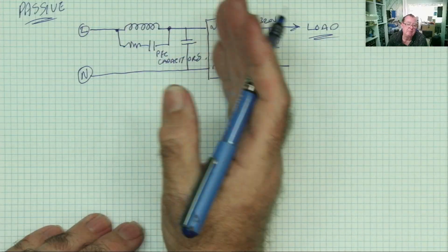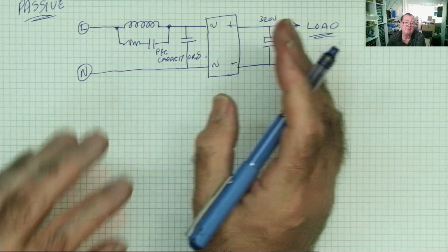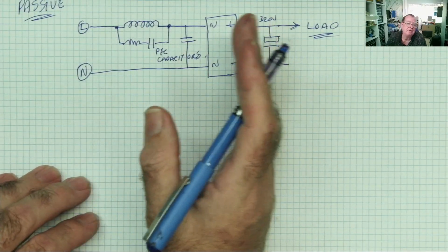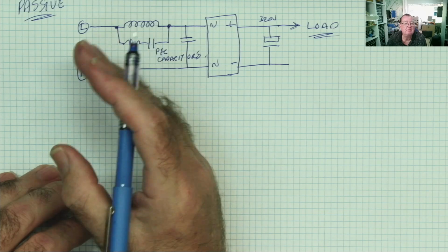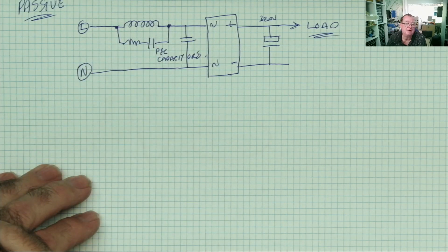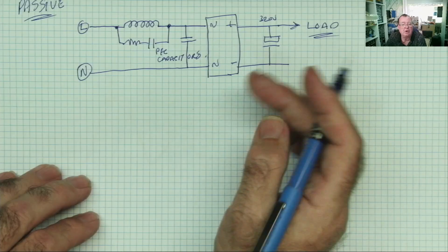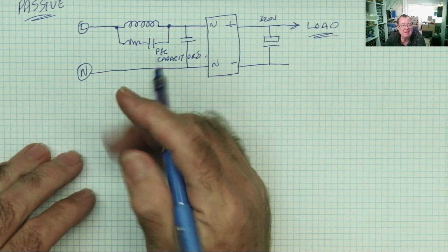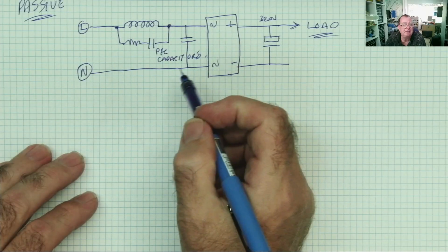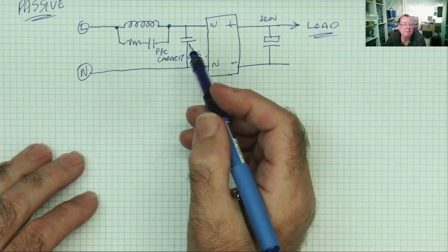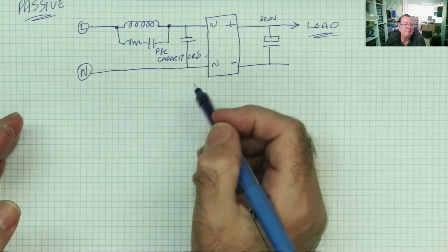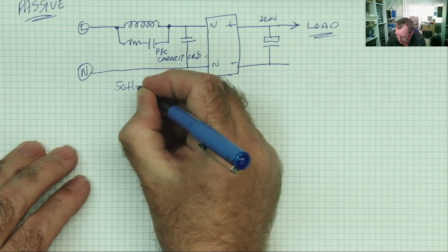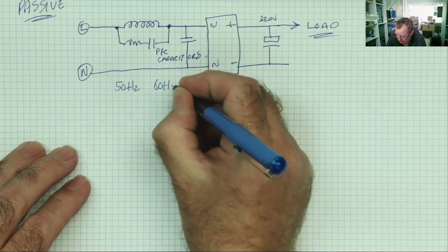This is also shifting it by a certain amount, and the combination of the two is intended to bring the phase between the current and the voltage back together again. The circuit is not 100% efficient or even 95% efficient. Because we have fixed value components, it will vary in performance at different frequencies. This is not really generally a problem because our mains is either 50 Hz or 60 Hz.